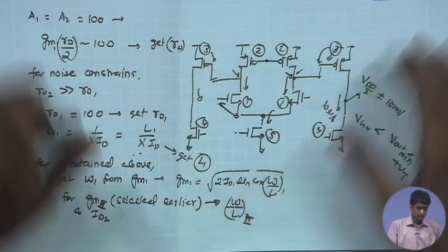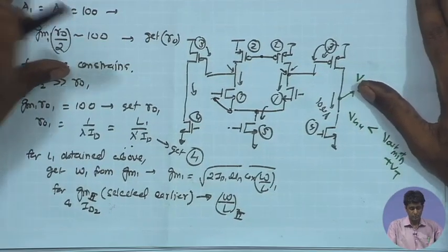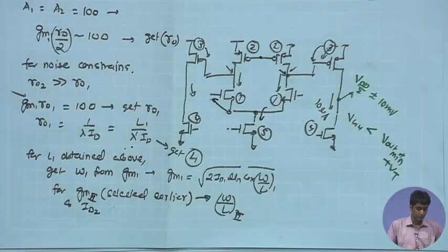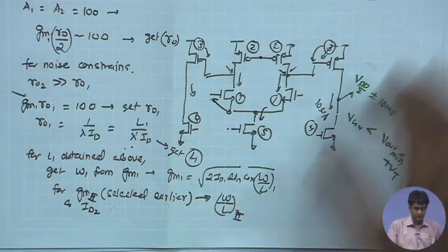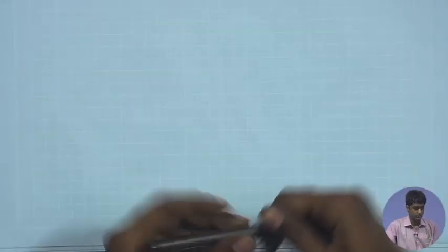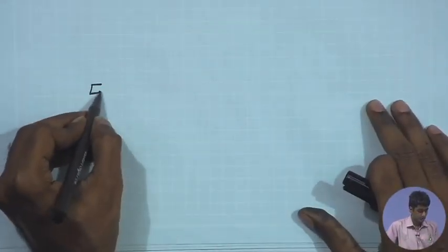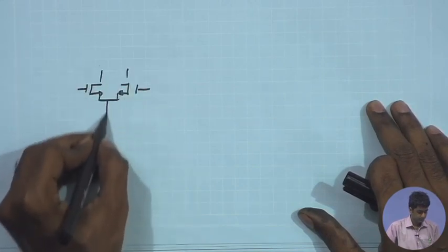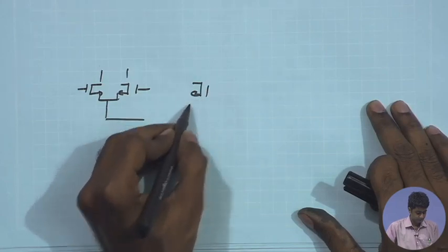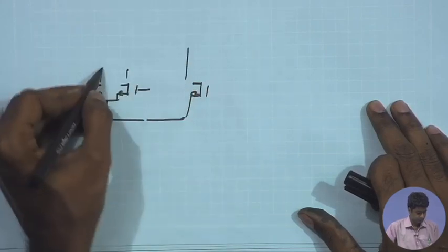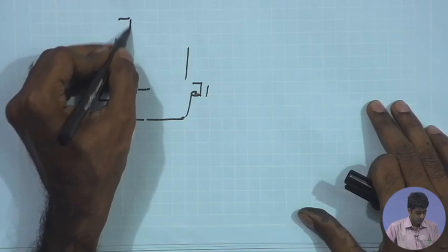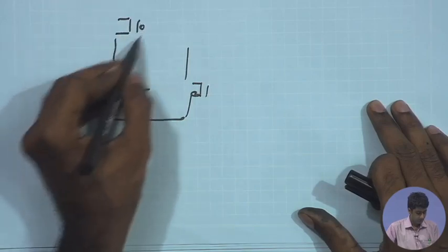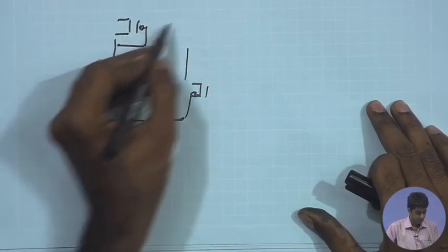There, some of the constraints related to the common mode feedback can be the input swing, meaning what is the input swing that the common mode amplifier can handle. So one of the important points that were discussed in the simulations also is related to the input device dimension, the GM of the input device. So if we are using, say, in